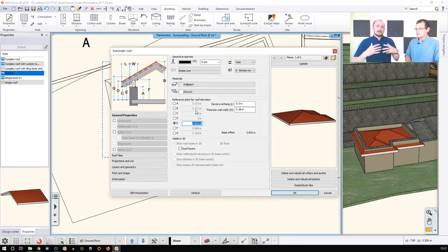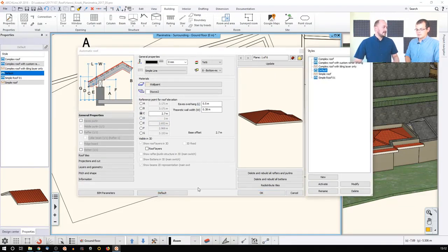Yes. So the software, based on the settings that you already have, is automatically recalculating the 3D shape and the 3D position of the roof based on the contour that you have created and based on the angles, which I will cover soon. So this is how you can build it up. Of course, when you work with these roof shapes, let me just go back to the default, you can also set up something we call a style. The software comes with built-in styles, not only in case of the roofs, but in case of the walls, slabs, and all the rest of the building parts.